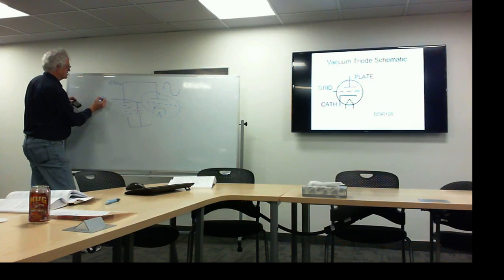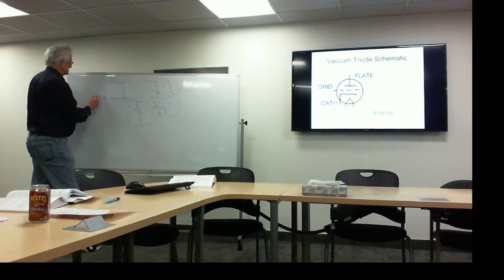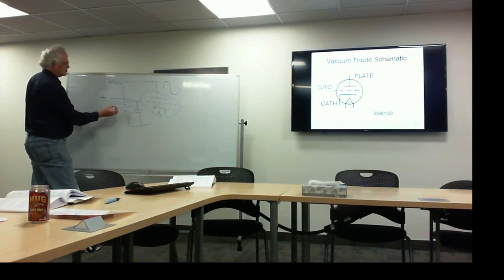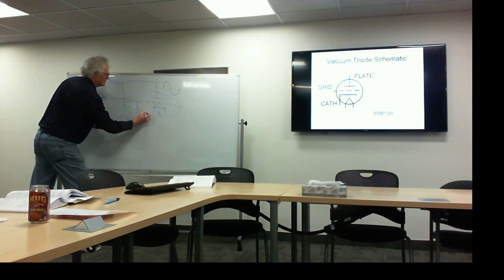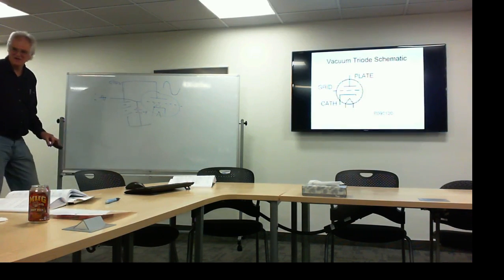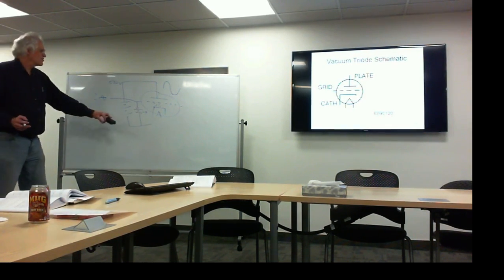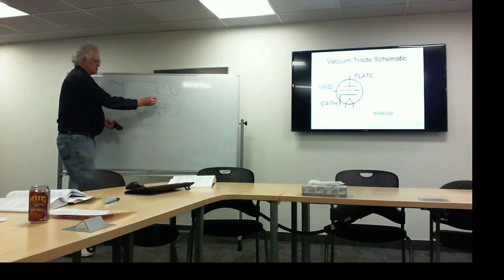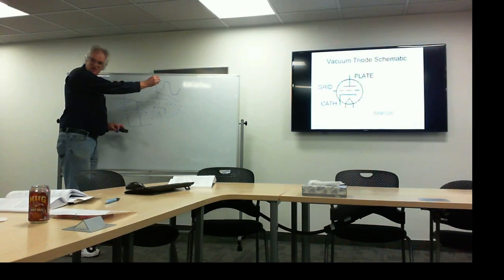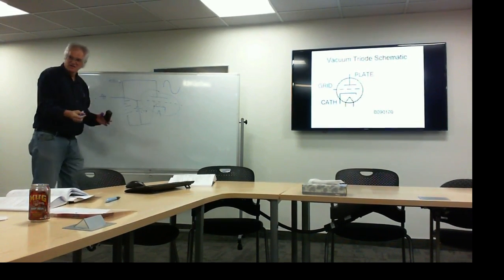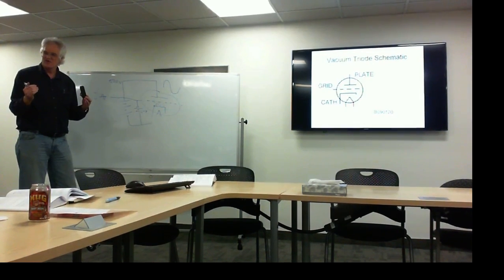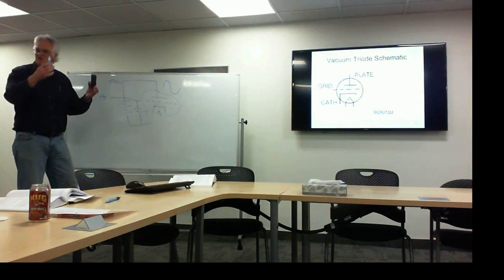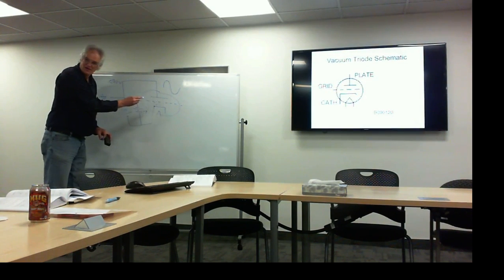this, +1, -1. So at this instant in time, +1 would add to your -10. That would actually make it -9, right? So now, by doing that, we're going to let more electrons through. Our current is going to increase, because we've reduced that control voltage, so now we're not blocking the flow as much. So the net current going through it is going to be bigger, right?